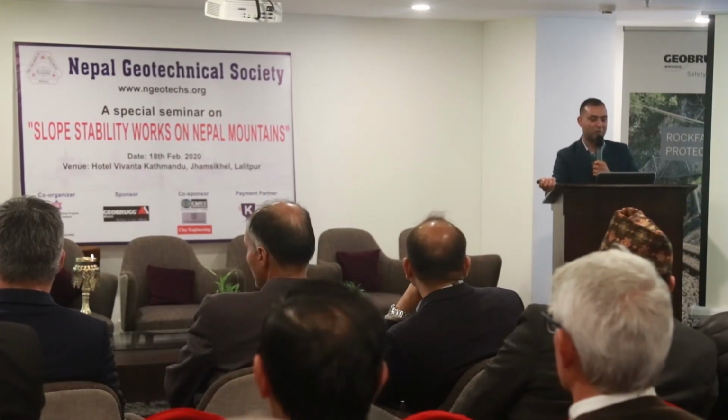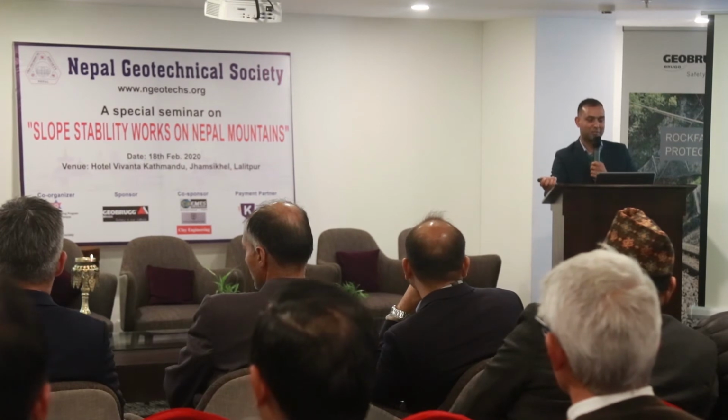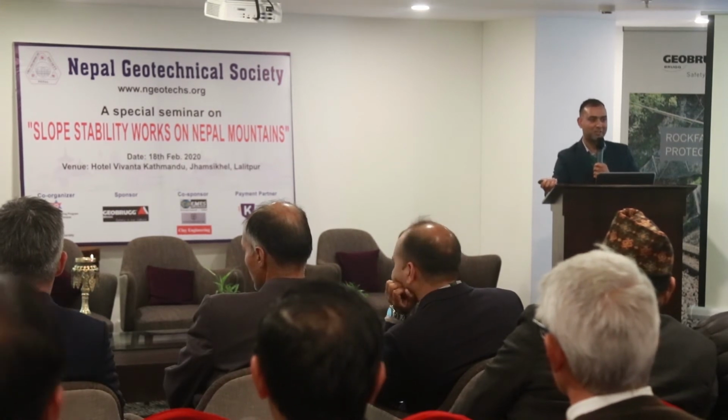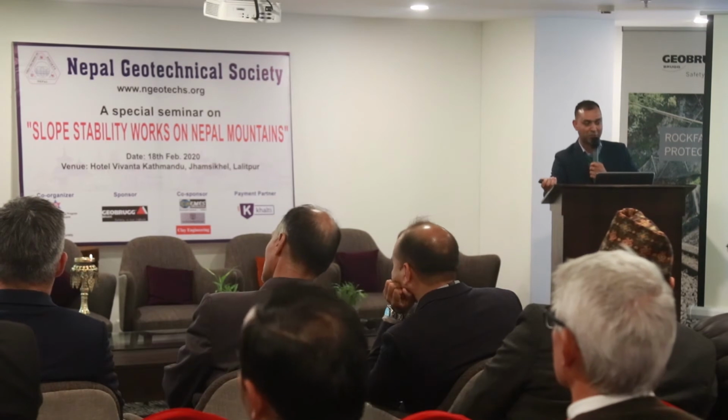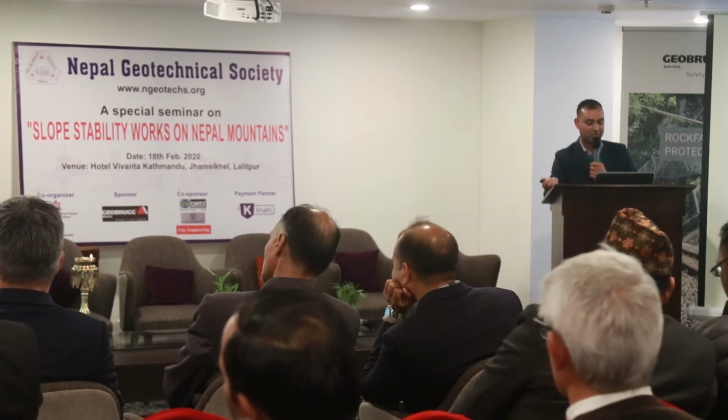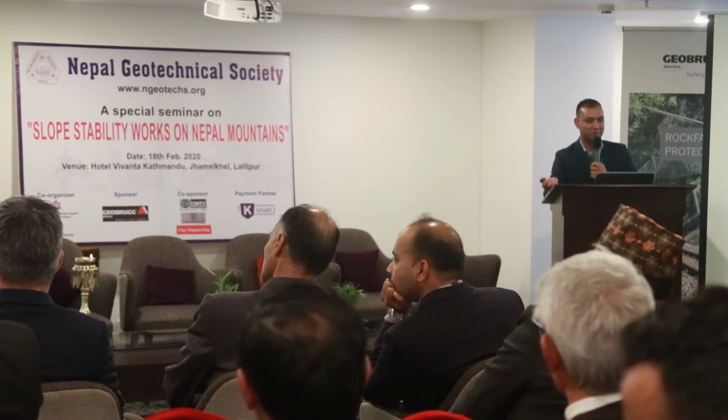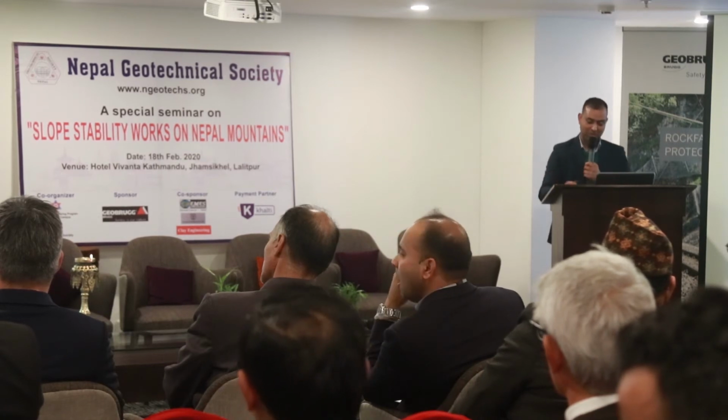So it's the toe cutting from the river. When they were building the road here, the river swelled in like a 100-year flood, and then it eroded the bottom part of the rock and colluvium wall. It's not continuously rock, but some part is colluvium and some part is rock, and it just cut the bottom, and it triggered the ridges on the top of the road, so it has to be protected again.